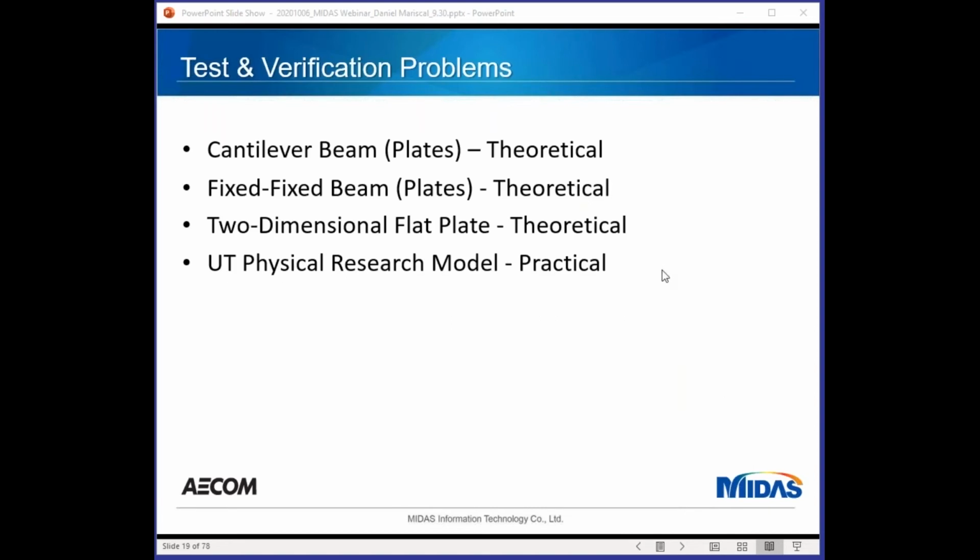So once we got the software, before we did anything with the project, we spent a considerable amount of time doing tests and verifications. We always, as engineers, want to make sure that the program is doing what we think it should be doing. So we did a cantilever beam made of plates. It was a reinforced cantilever beam, and we compared it against theoretical results.